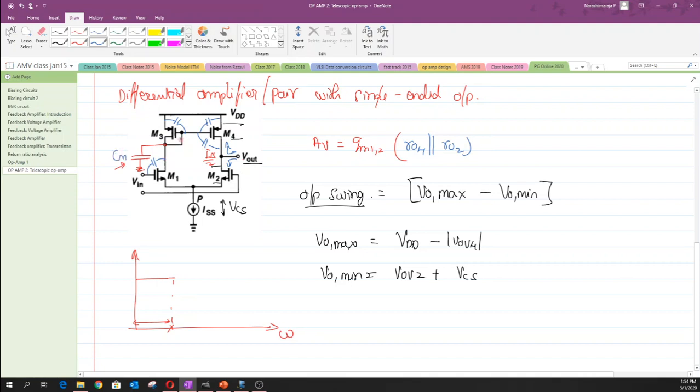And apart from this, when we look carefully here, you could see that the impedance value that we would have across this node will be approximately equal to 1 by gm3. Yeah. So we know that this pole frequency omega can be written as 1 by RC. Now for this node, the capacitance value is equal to Cm, but the R value that we have is basically equal to 1 by gm3, and due to which the gm3 will appear at the top.